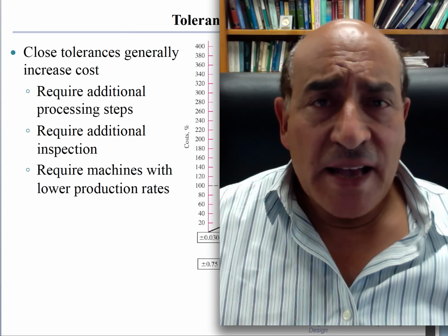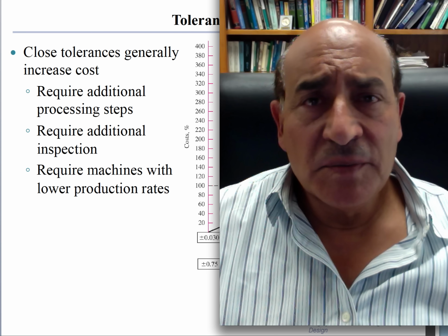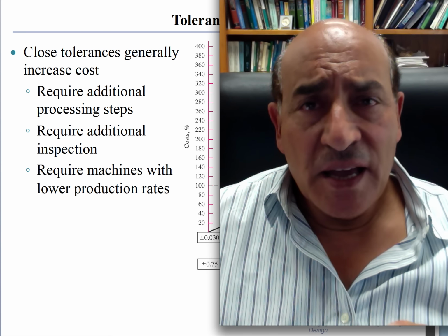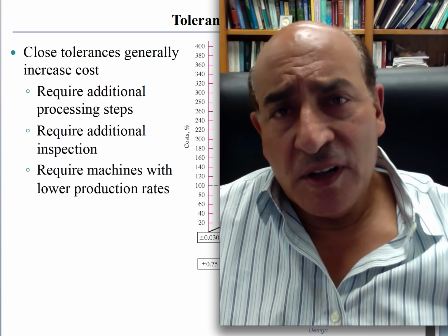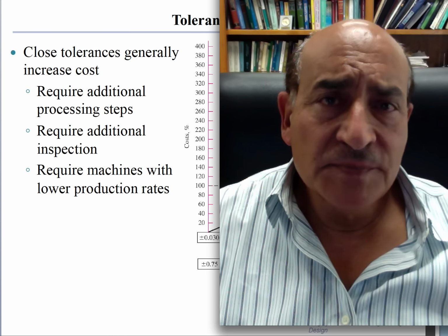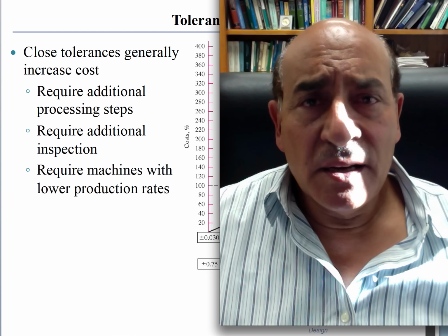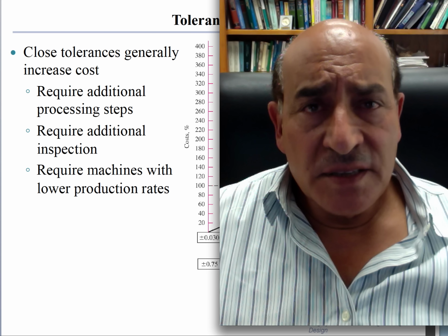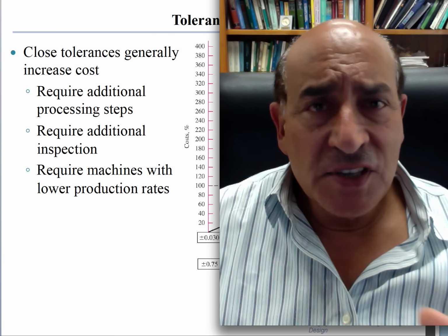The other aspect here is that if we are designing a product, I may have the option to select between two different methods. One, for example, could be certain manufacturing steps like handmade, where the labor is more involved in that process, human labor. And then another one that could be more automated. So if I'm comparing these two, consider manufacturing process A and B, I have to consider the startup cost for each one and also the cost per component. And generally, we'll find that there is a break-even point in our selection, depending on the number of units that we produce.